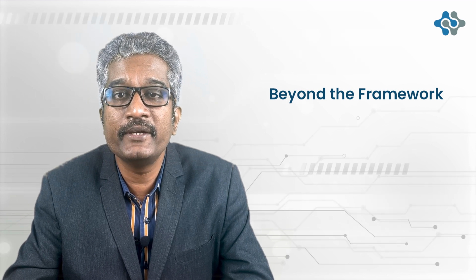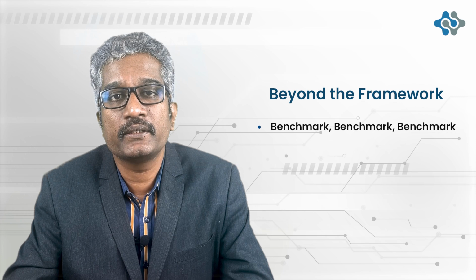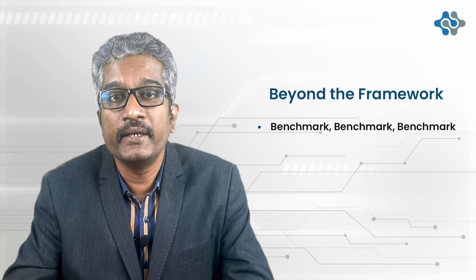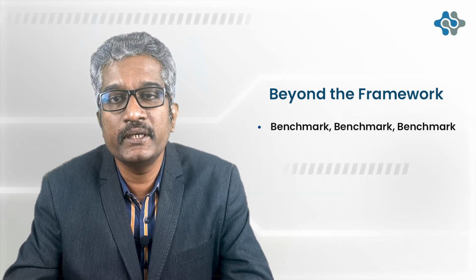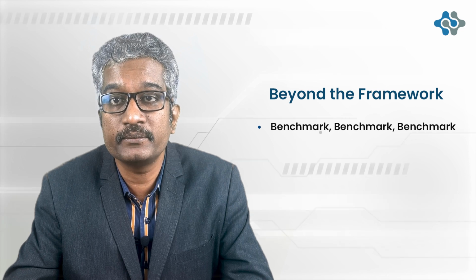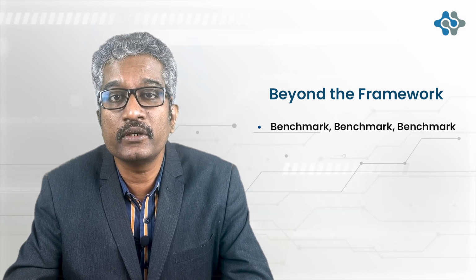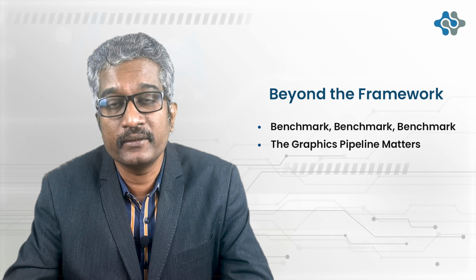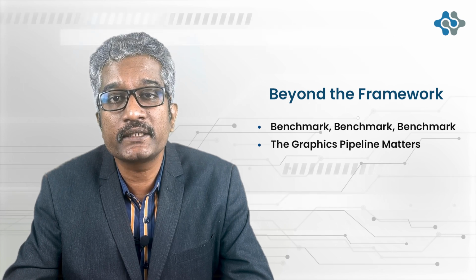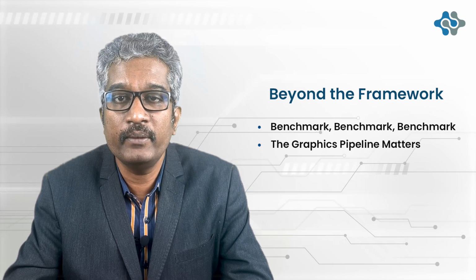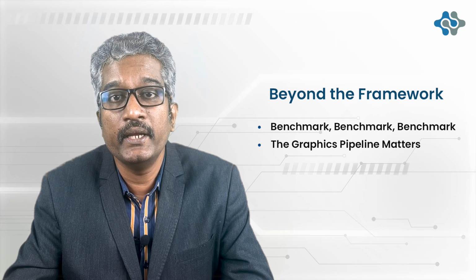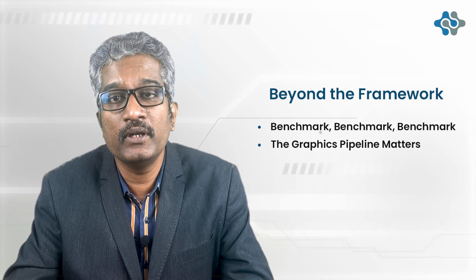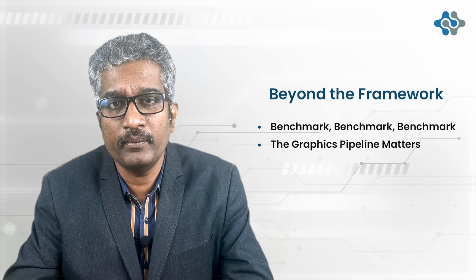Beyond the framework, expert insights. While these criteria will help you narrow down the field significantly, here are a few things my experience in the field has taught me. Benchmark. Never assume performance. Get a dev kit, implement a representative screen on your candidate tool, and measure rendering speed, CPU load, and memory usage on your target hardware. The graphics pipeline. Understand how the UI tool interacts with your specific display controller, frame buffer, DMA, and GPU. A tool might be powerful, but if the low-level hardware integration is poor, it won't perform.